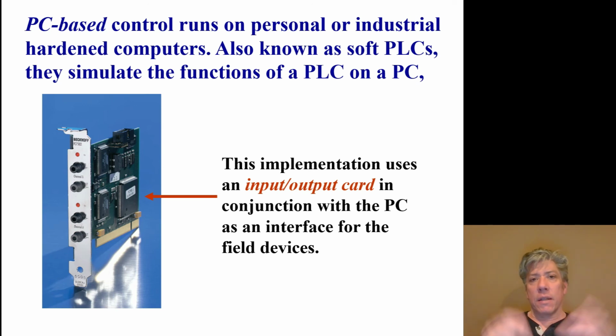But there's a lot of variety in this area, and you really need an industrial hardened computer, something that can take a little bit of abuse in terms of temperature and dust and so forth, because the goal of a PLC is for it to be easy to debug and change, but also for it to be able to work in an industrial environment. And one of the other problems with PC-based controls is if the I/O needs to be connected directly to the PC.